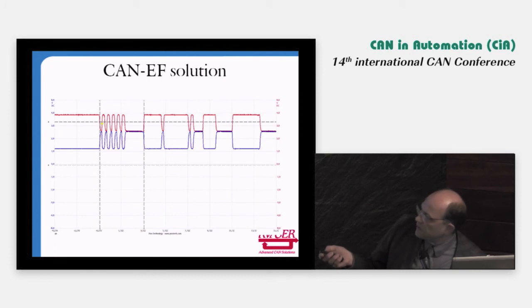So this is the beginning of a nominal classic CAN bit. And in the beginning here, we have the propagation segment, and the propagation segment is there only to handle the arbitration. So after the arbitration, every module will be in sync. That means we can add bits here, but we have to stop the number of bits here, because here we have the sampling point where the standard CAN will make the sampling. And now we have to stop our bits, so we are sure that all CAN controllers will have a correct sampling here. And then the next bit will come here, and we send more high-speed bits.